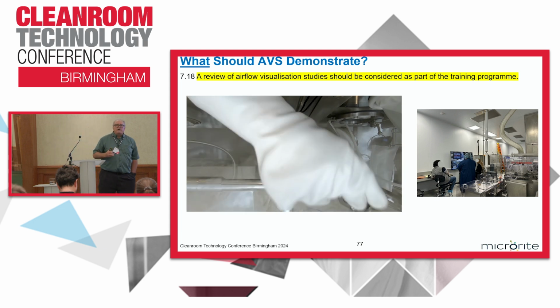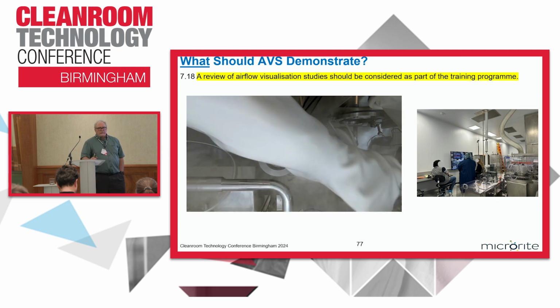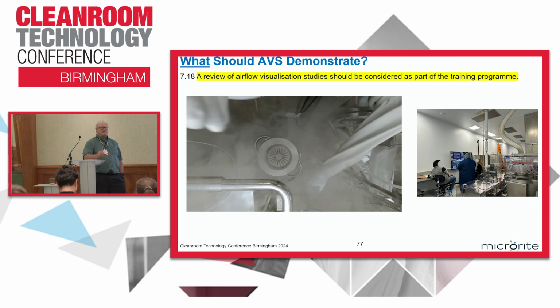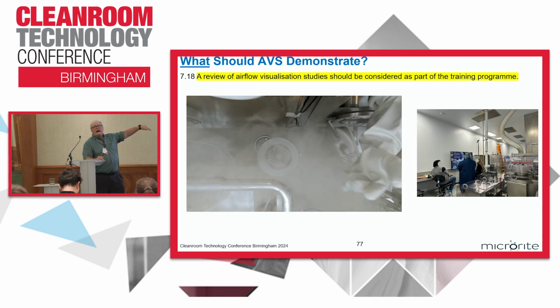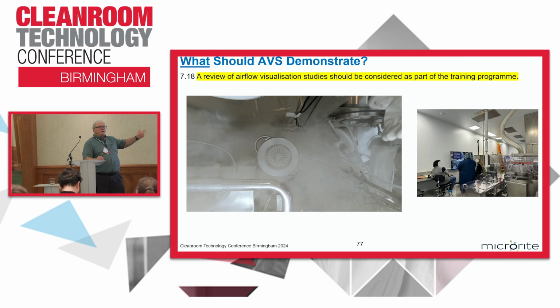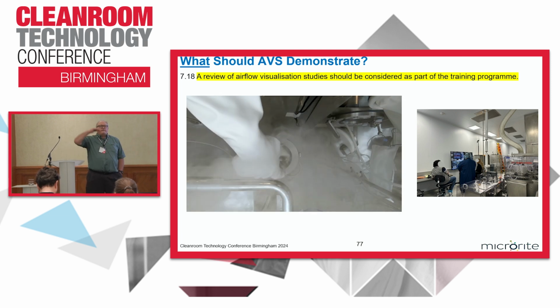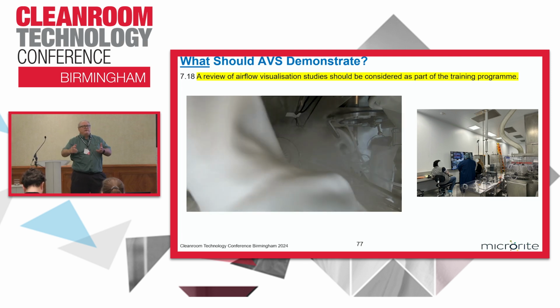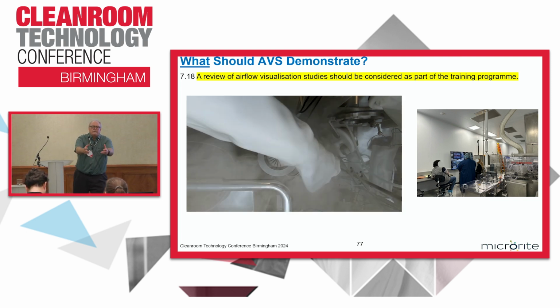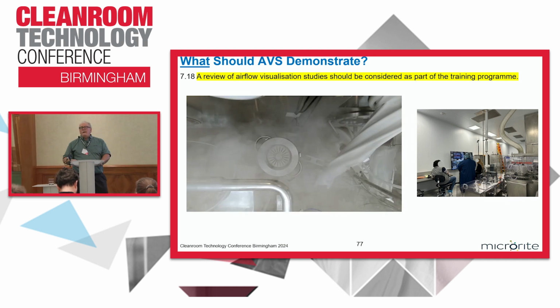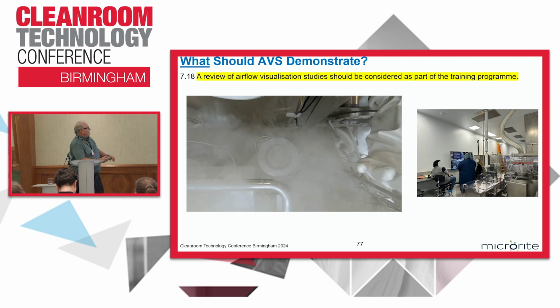You have the opportunity to coach your operators, right? We have SOPs. SOPs are great, and people should read them, but the problem is the implementation. And by having a team of people watch the operators perform it, you can tweak, you can modify, you can figure out issues like ergonomics. One facility we did, they had an operator that came up to be about this tall. And the partner that she worked with was about this tall. And they had to change positions because of the ergonomics, being able to reach through the glove ports into the enclosure. And smoke studies help put that on camera, help you film it, help you get an understanding of what's going on.